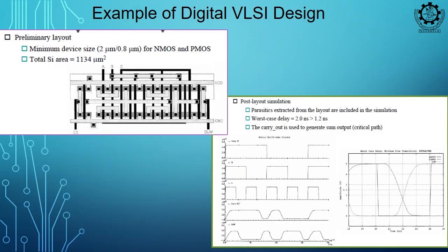So, this is after layout. If you consider the parasitic extracted model, then you will be seeing that in ideal case your input and output are mostly ideal. Okay. But when you consider the real parasitic model, you will be seeing that it is sloping down. Okay. If you have a bigger load, if you keep on increasing this capacitive load, then what will happen? Ideally, you should get a sharp edge, right. But as you keep on increasing this C value, what will happen?